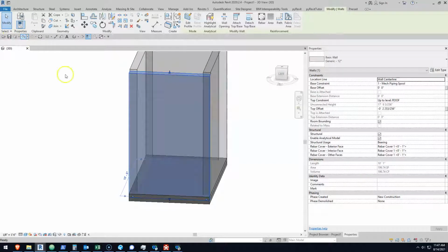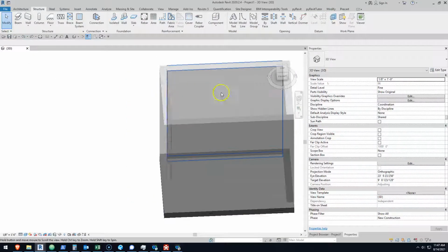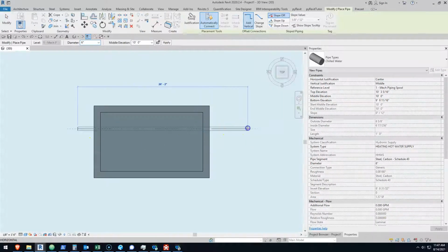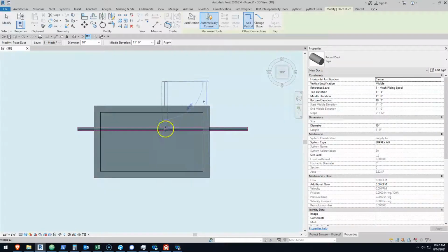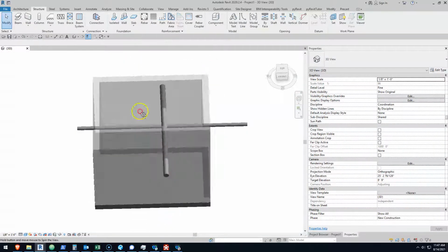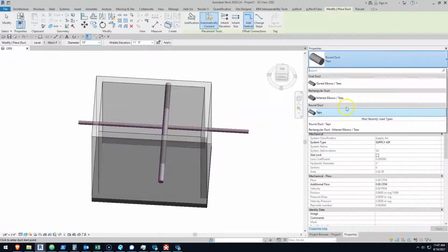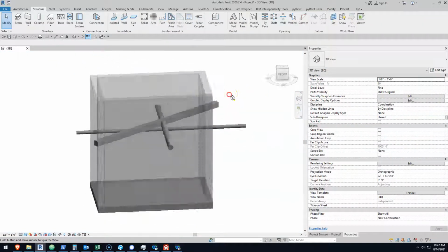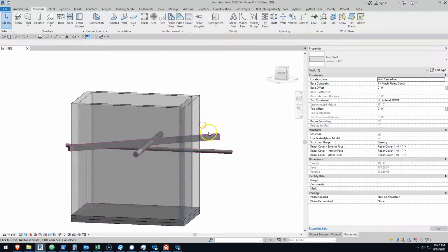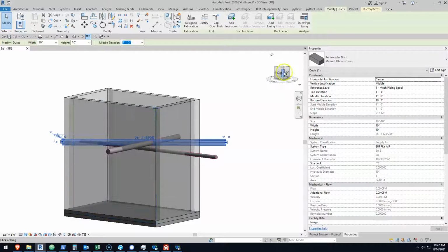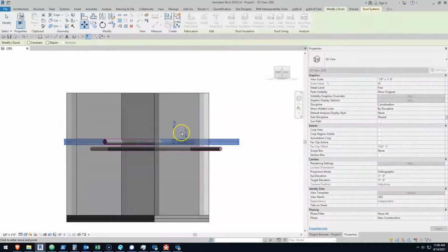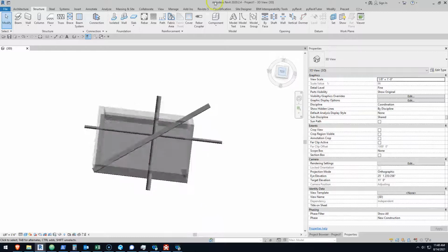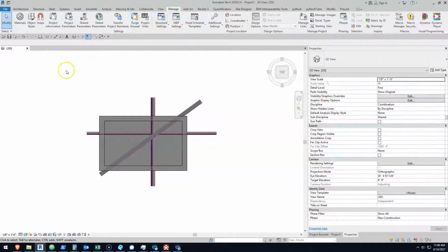And then moving on, once you get it modeled, so imagine you've got your building modeled, you've got piping services, ducting services. I'll draw a piece of pipe here. I'll draw some duct going across this other way. And then I'll draw some square duct as well, going across kind of in a diagonal. Okay. Now in 3D, it helps that you can see all this so that you can adjust all of your clashes. So you can do this directly in Revit. Revit has its own three-dimensional clash detection software that you can use. I think it's in Manage.